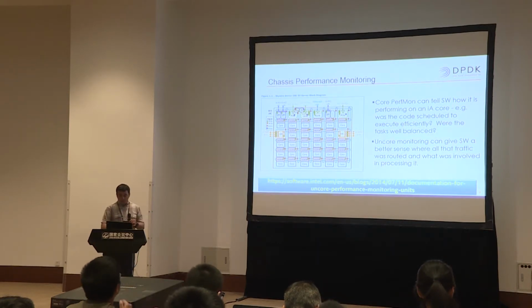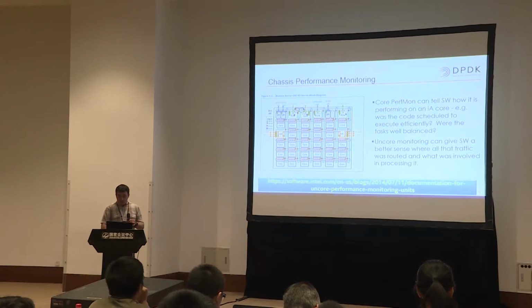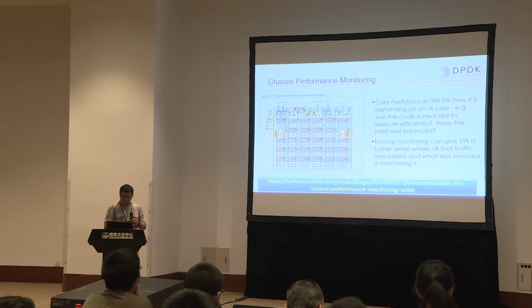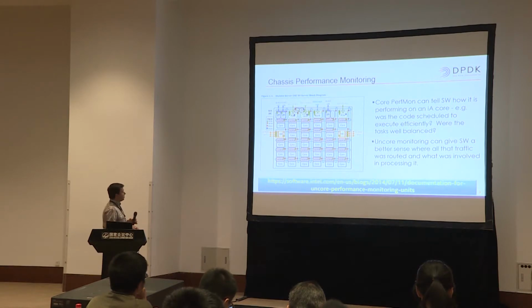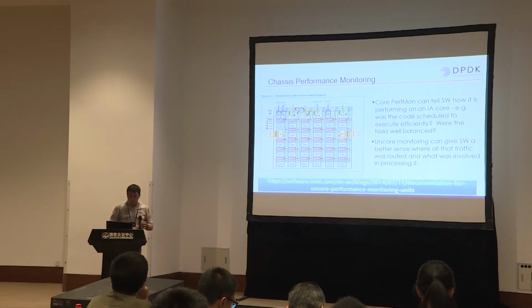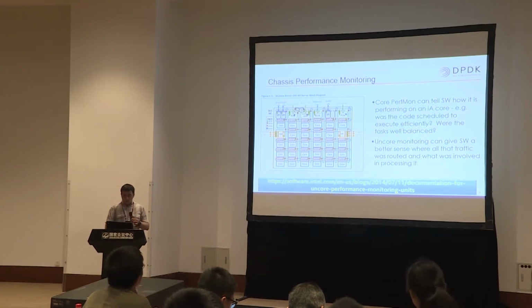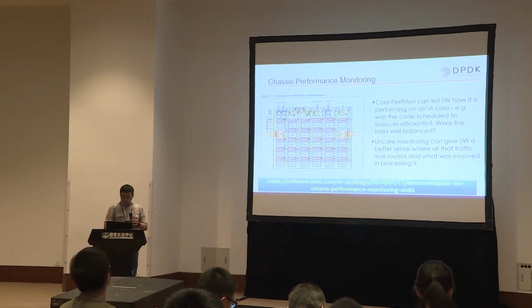However, when configuring a platform for I/O devices or when selecting a platform for I/O usage models, it's equally important to track performance from the uncore. And uncore is actually everything which resides beside the core. So it's socket interconnects, it's L3 cache, it's PCI Express subsystem, and memory controllers. Cumulatively, there are more than 1,000 performance monitoring events that can help understand micro-architectural activities while running an application.